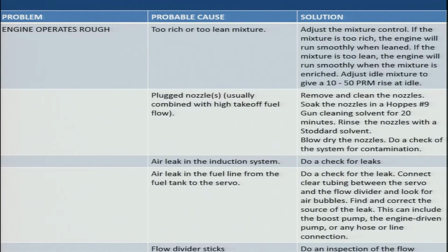So, it is better to send the flow divider to the servicing agency and replace it with a new flow divider. So, these were the several reasons why the engine was operating rough: too rich or too lean mixture, plugged nozzles, leak in the induction system, leak in the fuel line, flow divider sticking, flow divider faulty. So, we need to take rectification actions accordingly as per the manufacturer's guidelines.